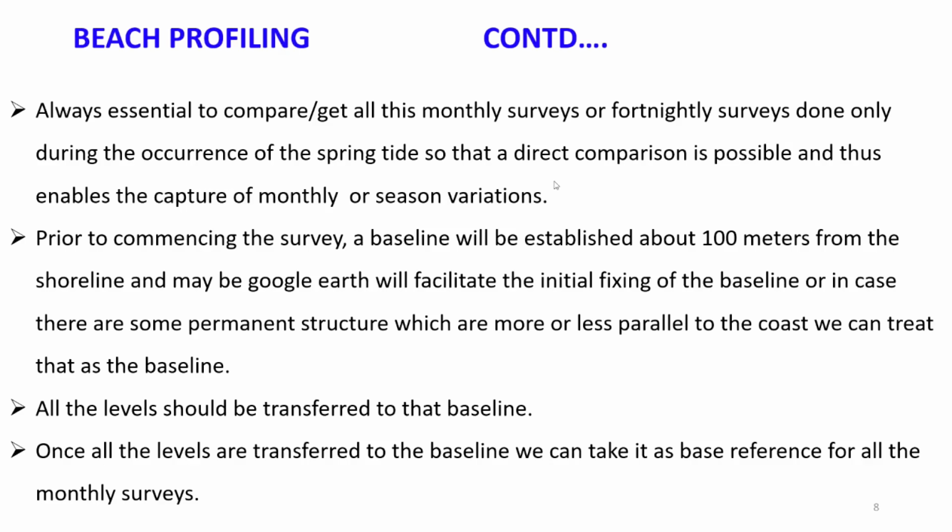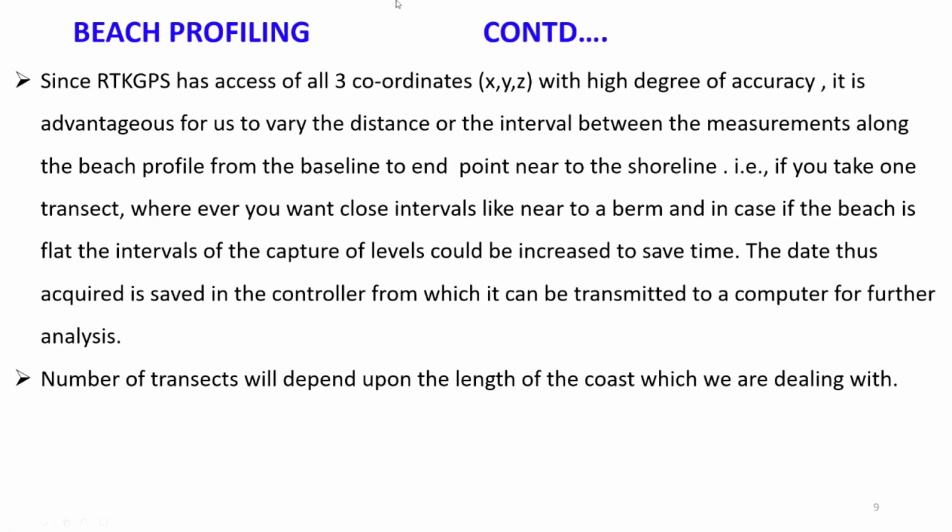Or you can look for some permanent structures, mostly parallel to the coast, that can be treated as a baseline. All the levels should be then transferred to that baseline which we are fixing. Once all the levels are transferred to the baseline, we can take it as base reference for all the monthly surveys.